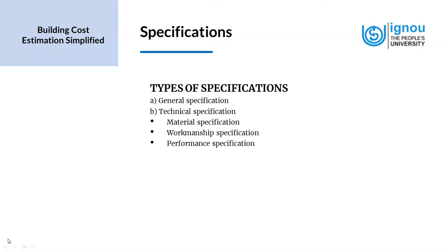Now, writing of the technical specifications must be coordinated closely with the preparation of designs and drawings. It is a good practice, as the designs and the drawings progress, to prepare an outline of the items of work that is to be covered and to write the technical specifications concurrently. In making the outline of specifications, the complete work must be analyzed carefully and all items and processes are to be noted beforehand.